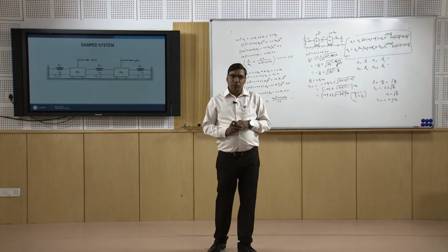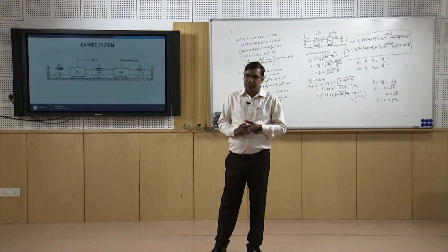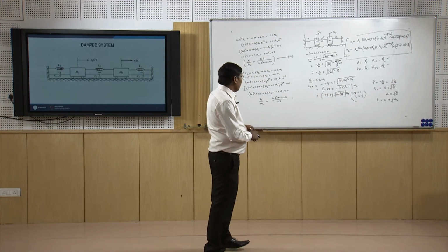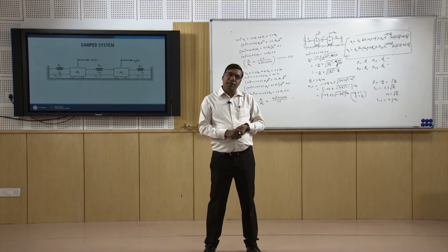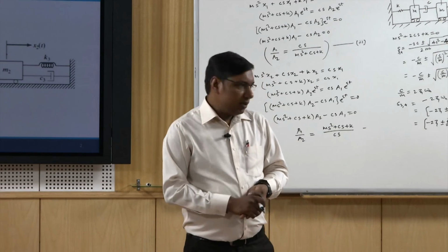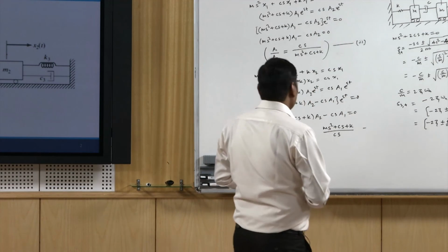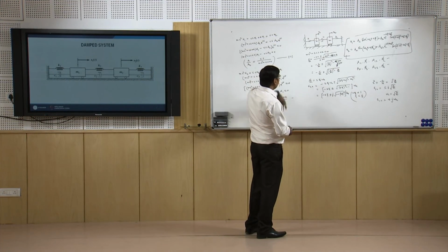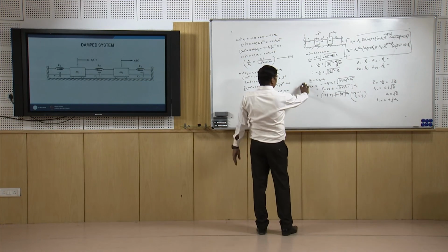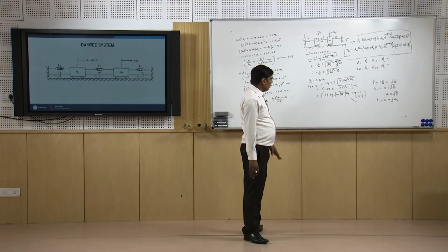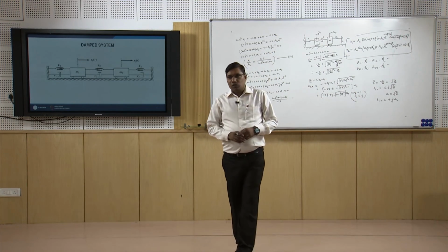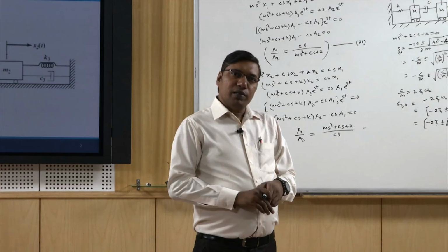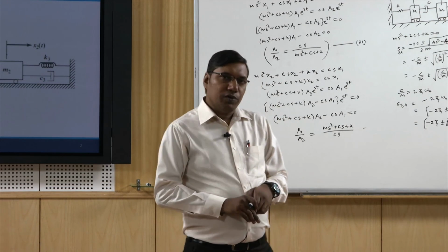However, if we give completely opposite initial conditions, then the system will vibrate with the damped free vibration. So the second part will be there, because if we put this S12 here, we will get A1 by A2 equal to plus 1, and when we put these values we will get A1 by A2 equal to minus 1. So in the case of omega n2, the system will vibrate as a damped free vibration.